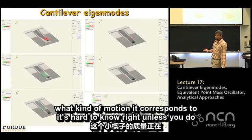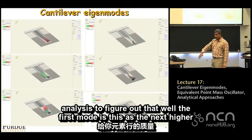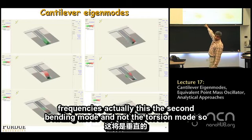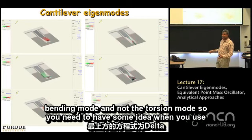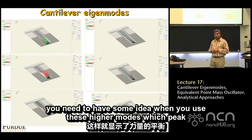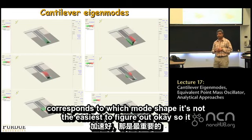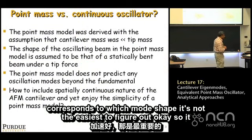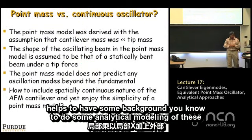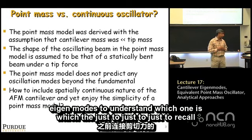Unless you do some sort of an analysis to figure out that, well, the first mode is this, and the next higher frequency is actually the second bending mode and not the torsion mode. So you need to have some idea, when you use these higher modes, which peak corresponds to which mode shape. It's not the easiest to figure out, okay? So it helps to have some background, to do some analytical modeling of these eigenmodes to understand which one is which.